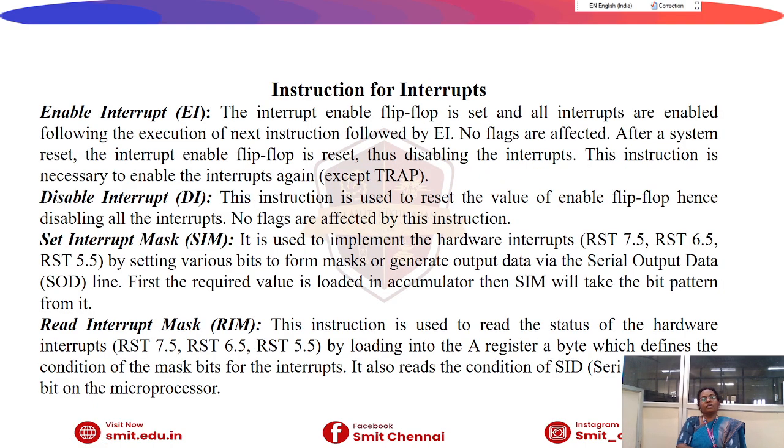Instructions for interrupts: enable interrupt, disable interrupt, set interrupt mask, read interrupt mask. These instructions are given for the interrupts. The first one is enable interrupt. The interrupt enable flip-flop is set and all interrupts are enabled following the instruction next to enable interrupt. No flags are affected.